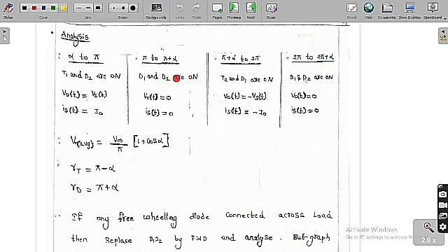Whereas from pi to pi plus alpha, here we have still not triggered T2, so T2 is open. Therefore D1 and D2 are going to conduct. So the output voltage is equal to 0 and the source current is equal to 0 in this case.